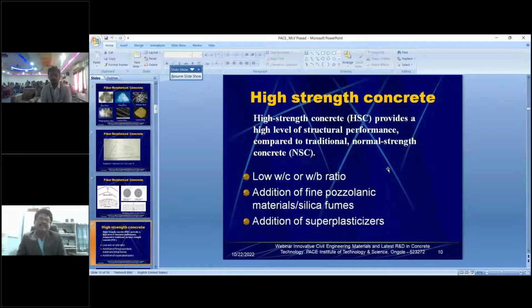Next, if you come to the high strength concrete, we already discussed the normal strength concrete. In normal strength concrete, we can achieve up to a grade of M50 or M55. After that, I am not able to develop the concrete. So suppose you are in metropolitan cities, or where the land cost is very high, in those cases definitely we have to go for high rise buildings. Let us say G plus 10, G plus 20, G plus 30, like that. If you are going like that, automatically you have to develop a high strength concrete, which is going to have higher strength characteristics. Mainly in the columns, we are going to use M60, M80, like that.